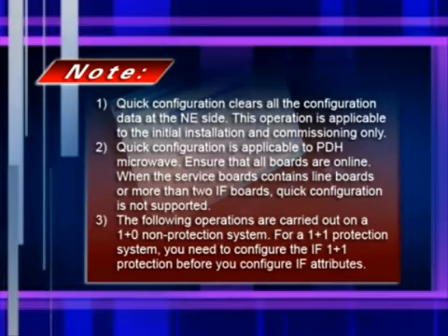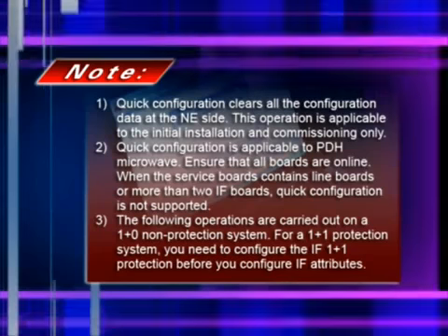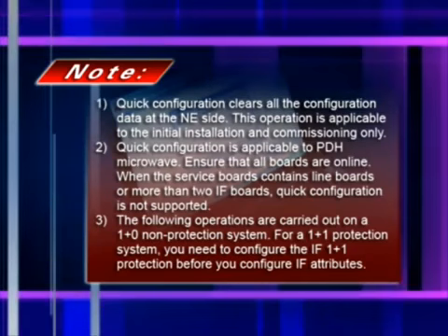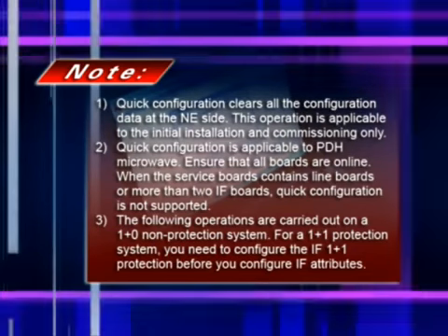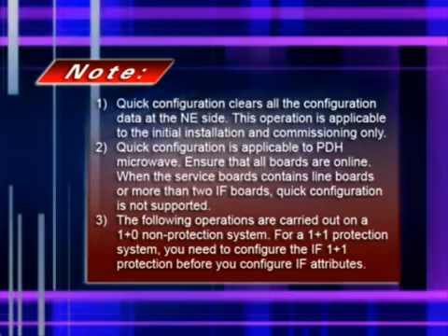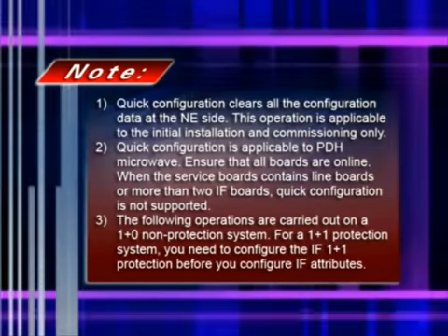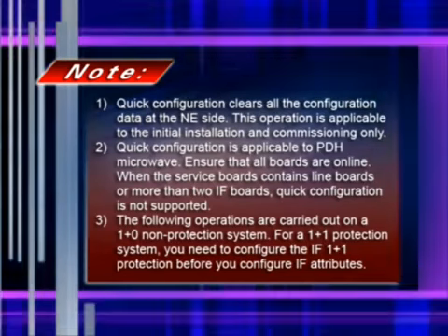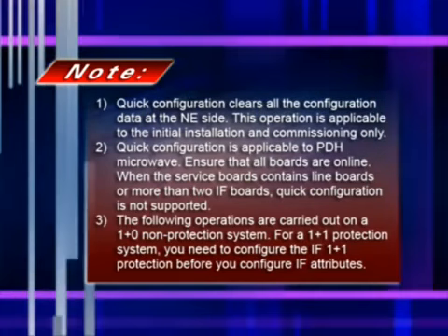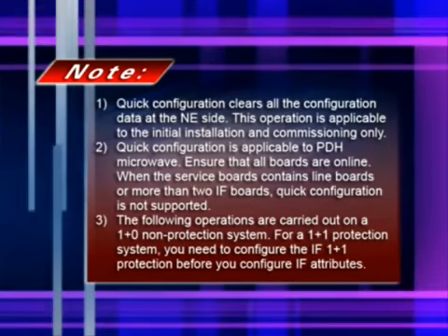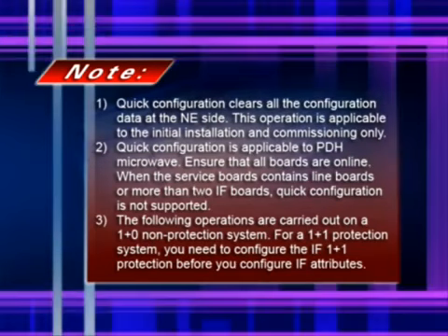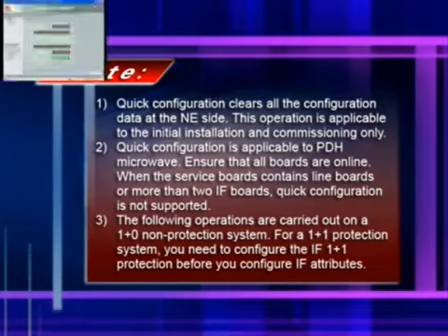Ensure that all boards are online. When the service board contains line boards or more than 2 IF boards, quick configuration is not supported. 3. The following operations are carried out on a 1+0 non-protection system. For a 1+1 protection system, you need to configure the IF 1+1 protection before you configure IF attributes.